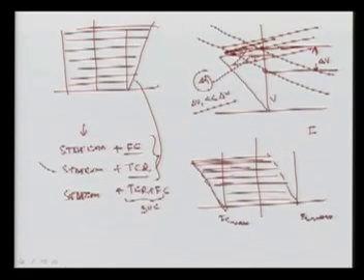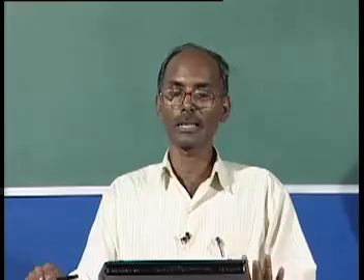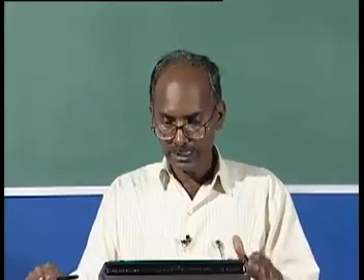Then we can have the fixed capacitor here, and the TCR as well. What will happen? We can maintain this one value with this variable, so we can go into this zone like this and get a very wide operating zone for the STATCOM, and then we can operate our system very smoothly. So basically these devices are very popular for improving power system performance, in terms of both static and dynamic performance.